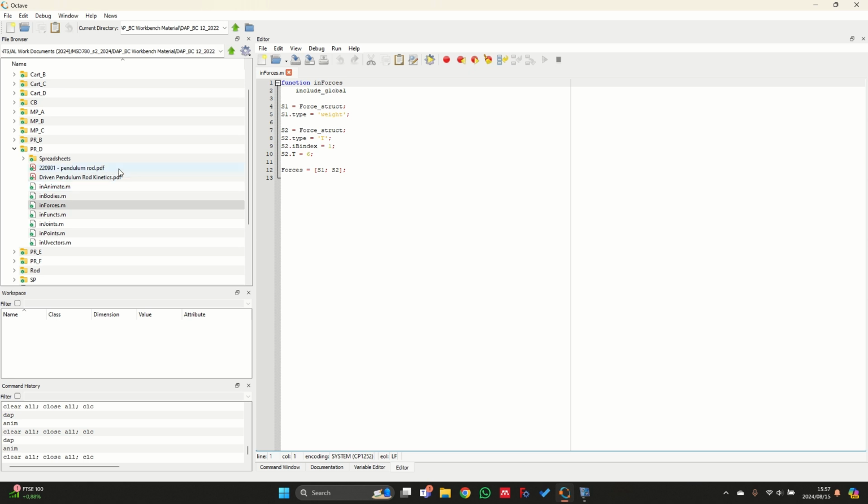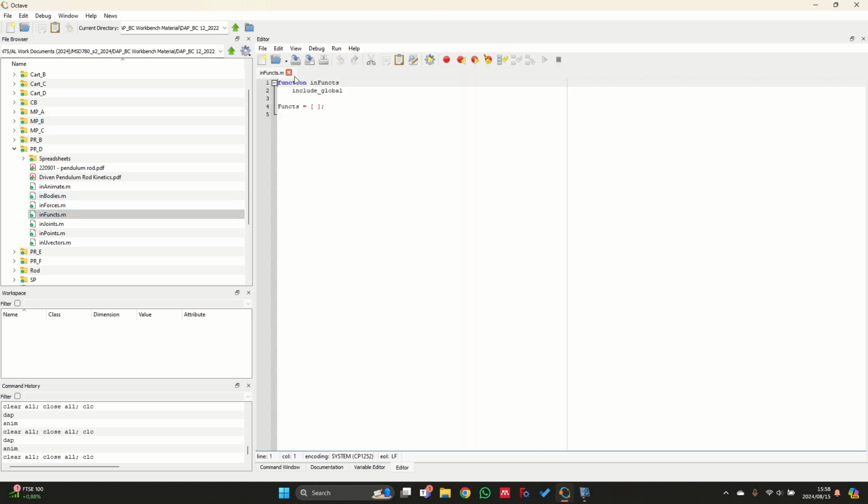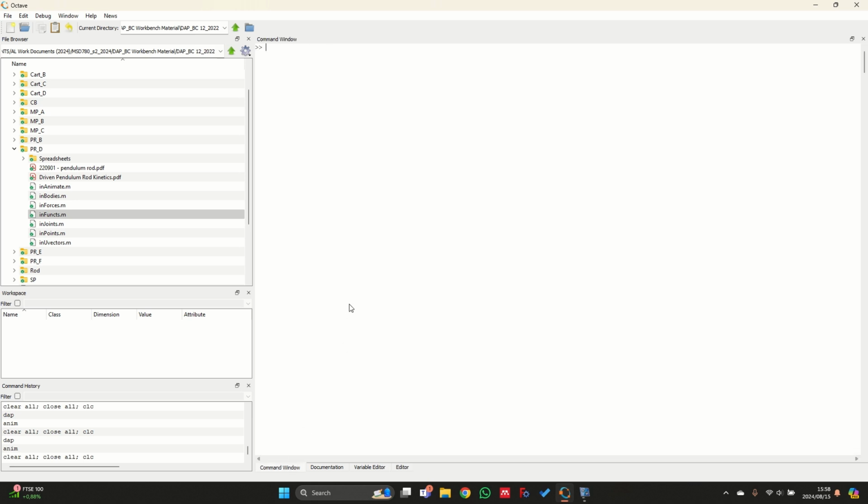We recall from the inverse dynamic analysis problem that the calculated torque that we need for a 2 pi over 60 radians per second square rotational acceleration was around 5.9. So now I'm going to make it smaller than that 5.9. Let's perhaps try something like 4.0. And I just want to double check that I don't have any function specified over here.